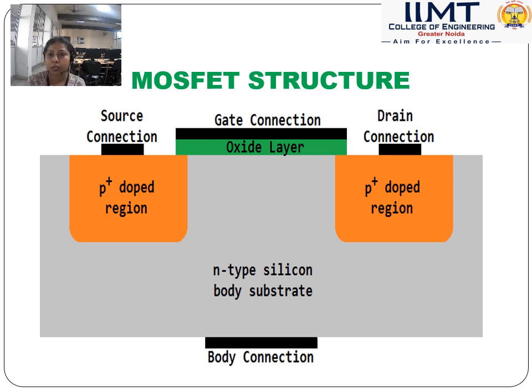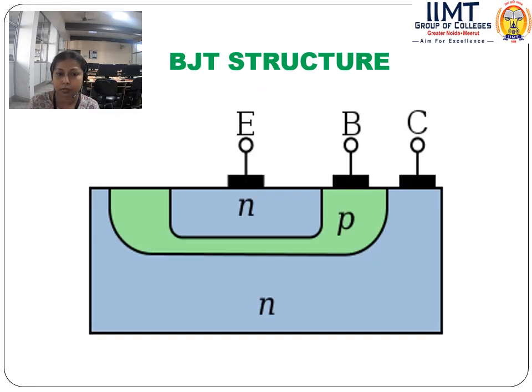Positive and negative photoresist mainly decide the fabrication of a structure, such as a MOSFET or a BJT. That's why the structures are shown before explaining the technique. Here, an N-type silicon substrate is used, with a P-type doped region, and a silicon dioxide layer must be fabricated over the silicon wafer before the doping process.